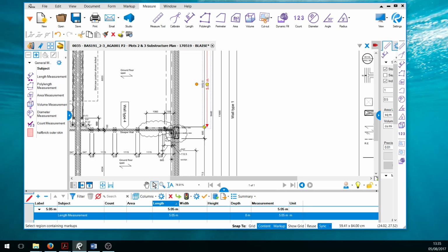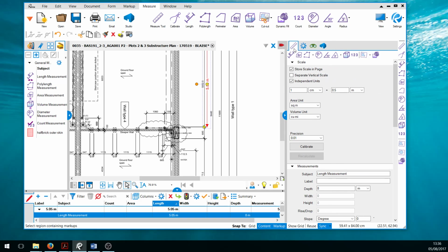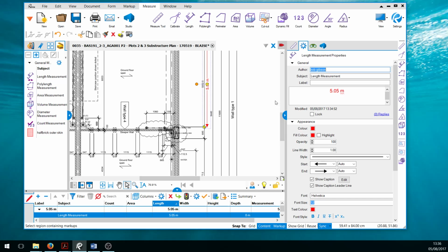So it's obvious what the length tool does, but before we move on to the next tool, over here on the right pane, if you click on the little cog, a dialog pops up, and that's what gives the length tool its style and properties. That's why it's a red line, that's why the length is shown, and the style of arrow and the font it uses, etc, etc. This is where we will come when we want to create our own tools.